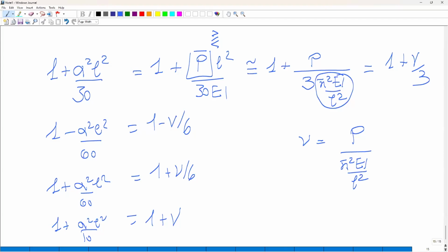So the check engineer should repeat some of the calculations, not all of them. Surely the check engineer does not run the whole structural model, because it's not his responsibility, and because the fee for the check is not the same as for the design. So he will not run the whole structural model, but he will repeat some simple calculations.